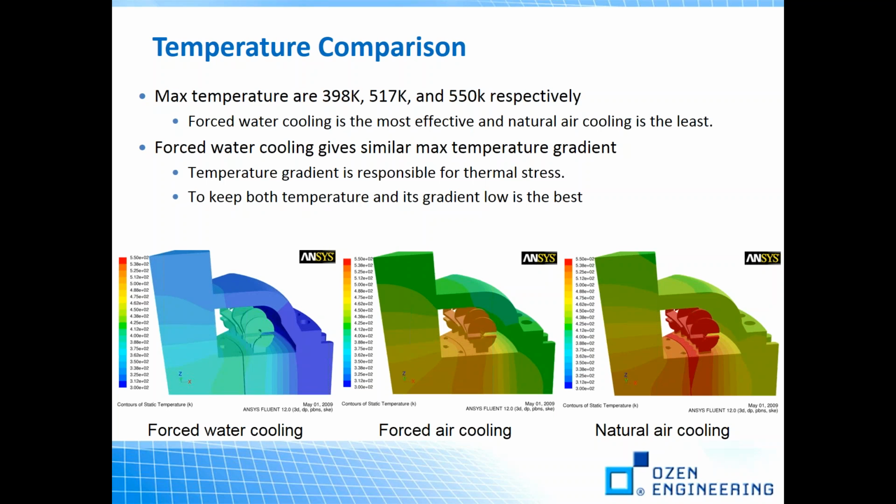There are different methods for cooling. You can see the different methods: forced water cooling, forced air cooling, and natural air cooling, and look at the temperature of your device. Basically, forced water cooling is the most effective, and natural air cooling is the least effective here.